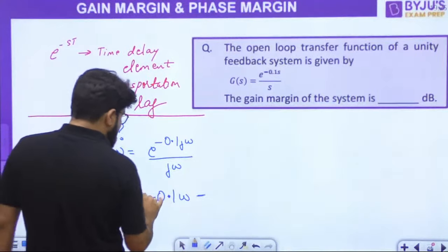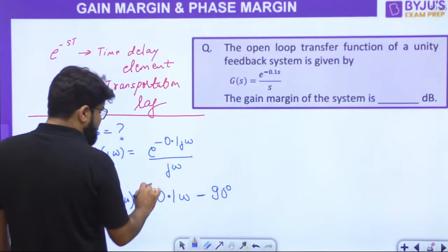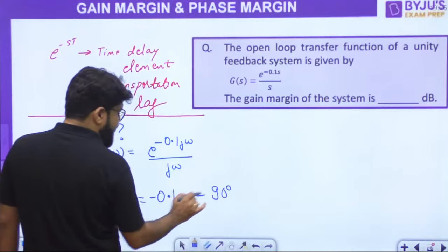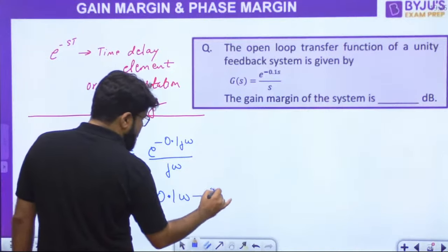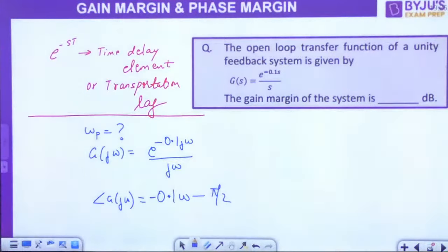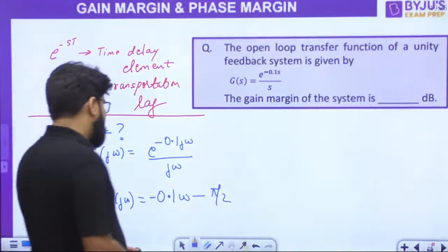What is the possible mistake? Minus, commonly we write 90 degree. But when you write e power j theta, theta is by default in radian. Radian and degree will not go together. So either convert this to degree or write 90 degree as pi by 2, both in radians. But not required, Srinath. So this is the angle expression.